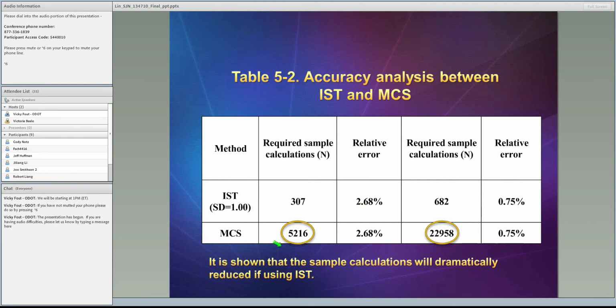And additional work too for the multiple rows of drill shaft stabilizing slope, which is a deterministic methodology part here. So why are we using multiple rows of drill shaft? There are two major reasons. First one is target factor of safety. The factor of safety using one row of drill shaft cannot satisfy the target, no matter how we choose the dimensions of the drill shaft, the spacing, and the locations.